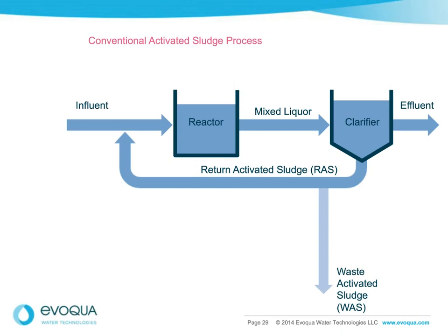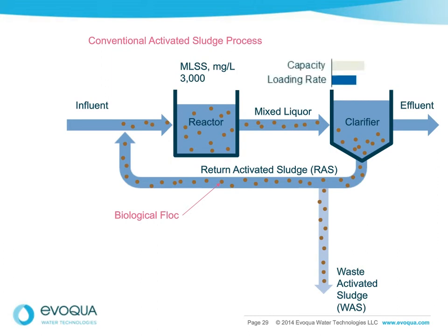Now, if you have an increase of your influent flow or contaminant loading on your clarifier, you may have to run at a higher mixed liquor, or there may be a change in temperature. And that may result in where you're getting close to a solids loading capacity limitation on your clarifier. And when you do that, you may start seeing solids start floating up out of your clarifier.